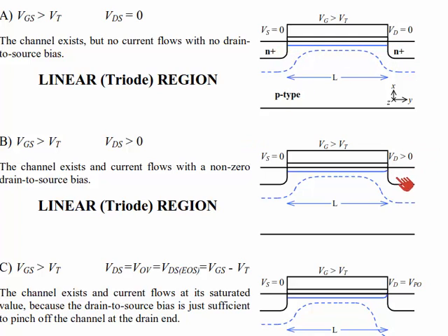If we increase the drain voltage slightly, so VDS greater than 0 because of VD greater than 0, then we send the drain-to-body junction, this PN junction, into, and I'll ask you to think of whether it is forward or reverse bias. We apply a positive voltage on the N-type drain. In fact, pause the video to think about it before continuing. If we apply a positive voltage to the N-type drain and a more negative voltage to the body, we reverse bias the PN junction and widen the depletion layer width.